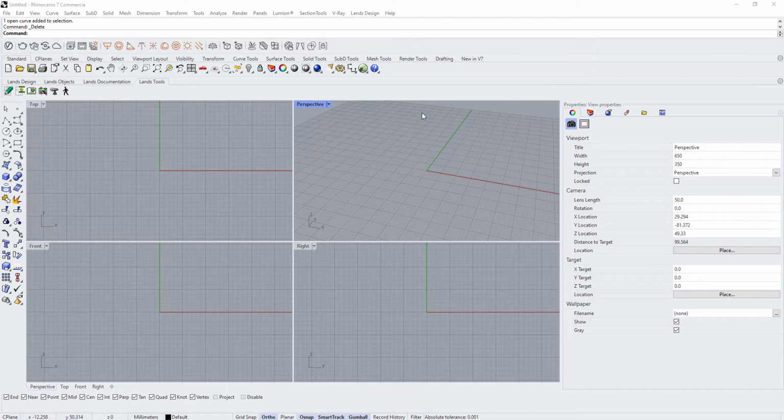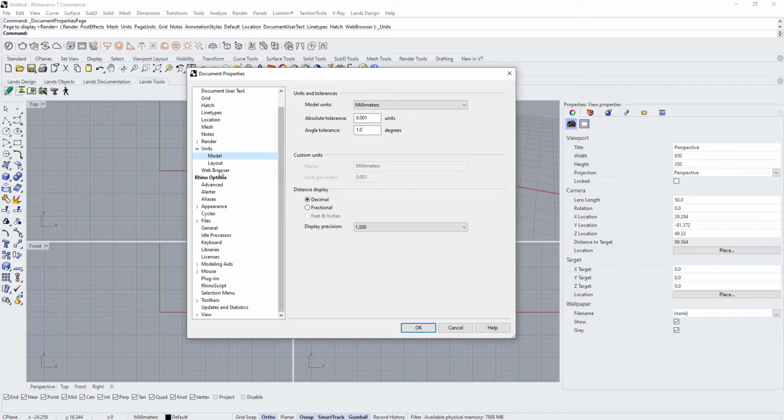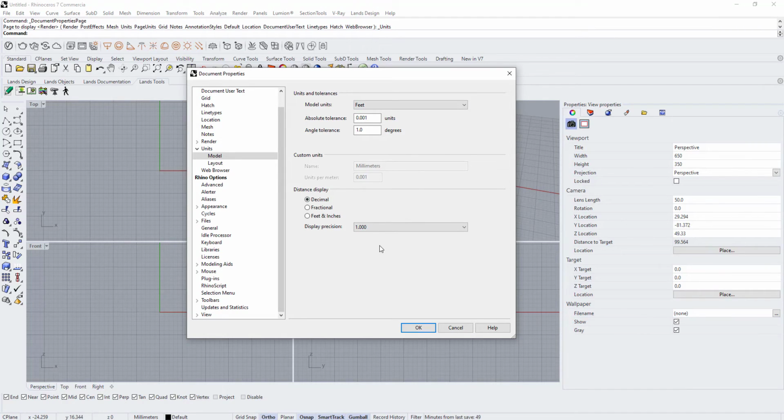Another part of housekeeping is setting up the units. In order to do that, all we have to do is type in UN, and this will come up. From millimeters, we just have to set feet and decimal feet. Or if we have any CAD drawings, set up the units just like the AutoCAD that we have set. But if we are using the template from the department, it will be decimal feet. So this is the correct unit to set.